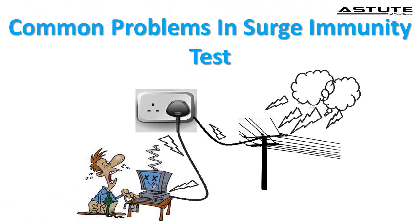Common problems in surge immunity of devices, given below. Surges generated due to lightning strikes, power outages, tripped circuit breakers, due to short circuits, power transitions in other large equipment on the same power line, malfunctions caused by the power company, electromagnetic pulses with electromagnetic energy distributed typically up to the 100 kHz and 1 MHz frequency range. Inductive spikes due to magnetic and inductive coupling.